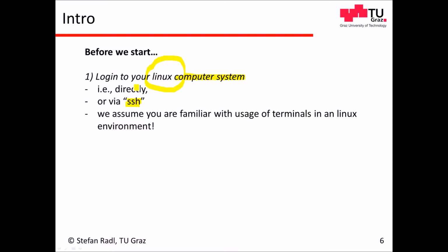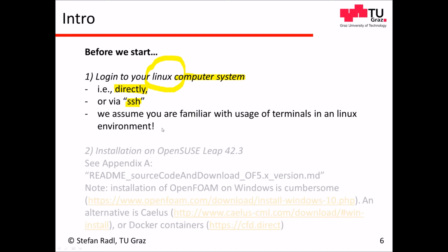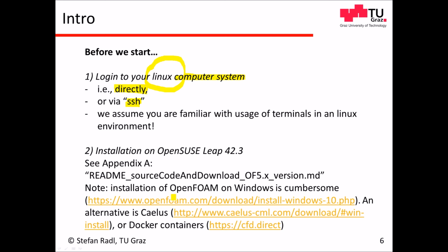Or of course, what is also very often done is that we have a Linux workstation just at our desk, and we switch over to this Linux workstation whenever we feel we need to do our simulations. There are specific installation instructions for OpenSUSE Leap that I have put together. There is an appendix that you will also find in the material provided, and this explains in great detail how to install and compile OpenFOAM on OpenSUSE Leap 42.3.